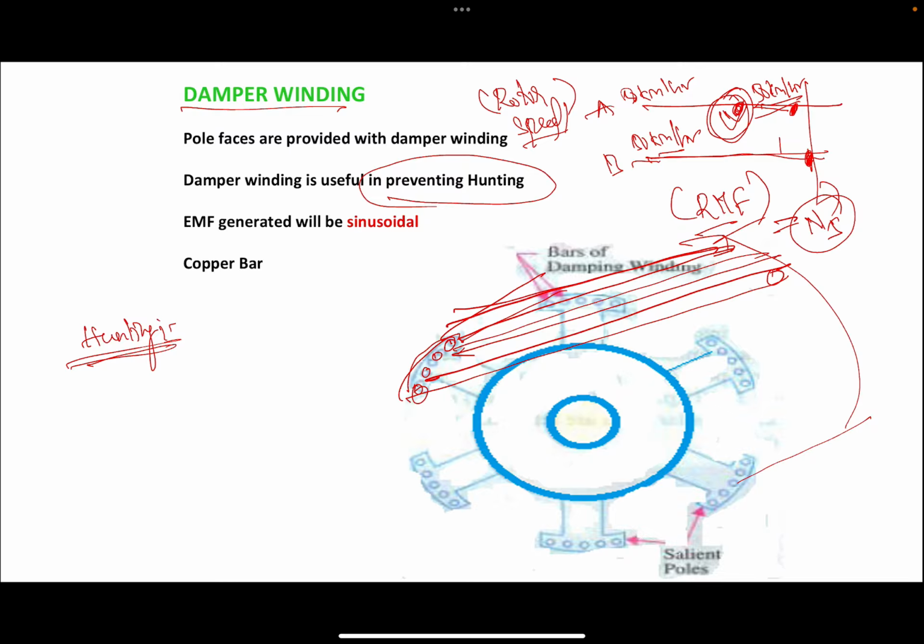I am just explaining in a generalized way. After the disturbance, it overcomes the disturbance, and again the rotor starts rotating at the same synchronous speed. But due to that disturbance, whatever the 1 or 2 seconds of disturbance time, the rotor is not in the same position with respect to the rotating magnetic field. Though the rotor is now rotating at 1500 RPM, it is not in the same position as the initial position with respect to the stator.